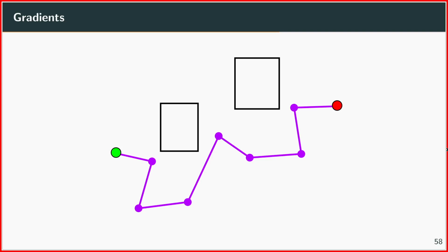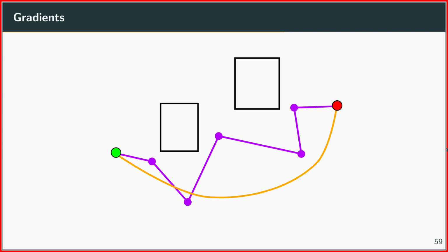And so, how this would look visually is basically that you get as input again some kind of zigzag path, and then you have something which would be maybe like the optimal path here. And what you do is basically that you compute for each waypoint here a gradient, and this gradient basically points you in the direction of where lower cost would be for this path.